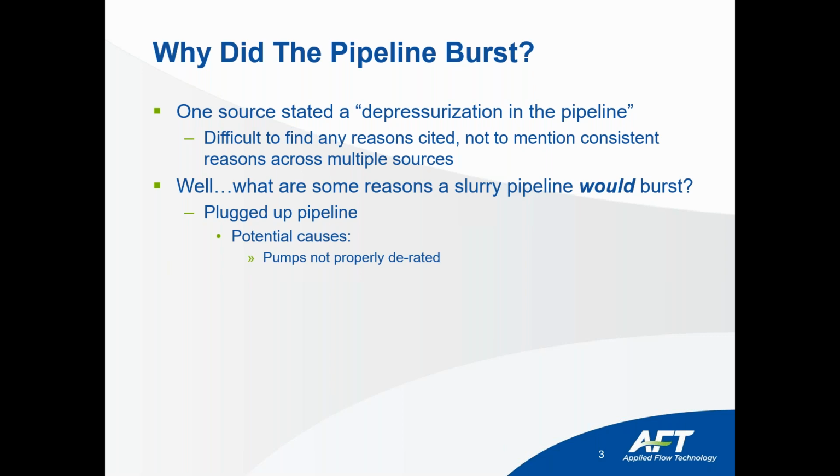Other issues are where you have not properly derated your pump performance for pumping a slurry. Keep in mind that the pump curves that you get from the manufacturer are typically tested with water, so they're not going to perform the same when you are trying to pump a slurry through them.